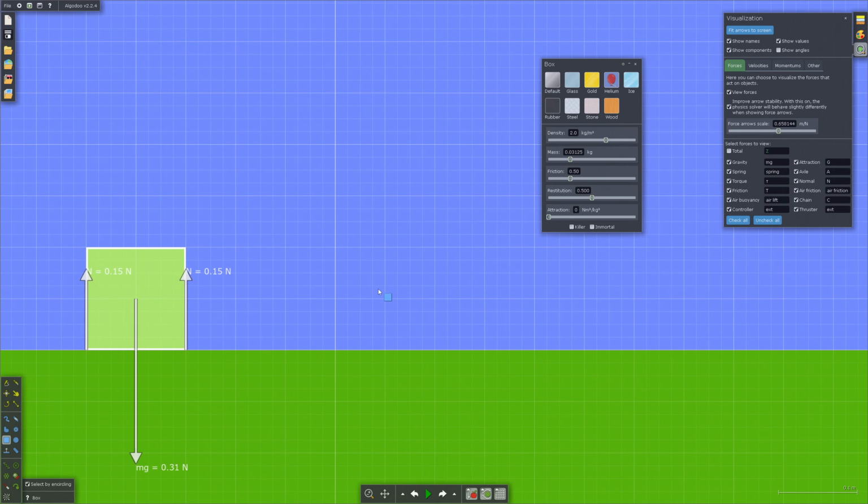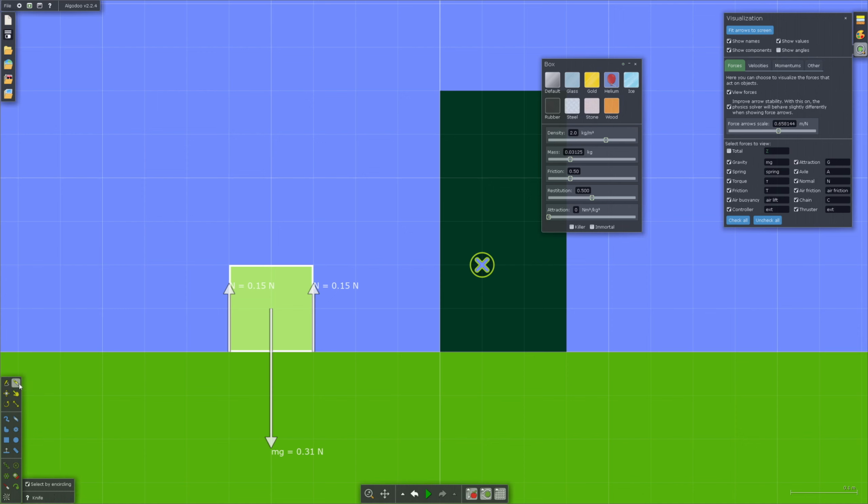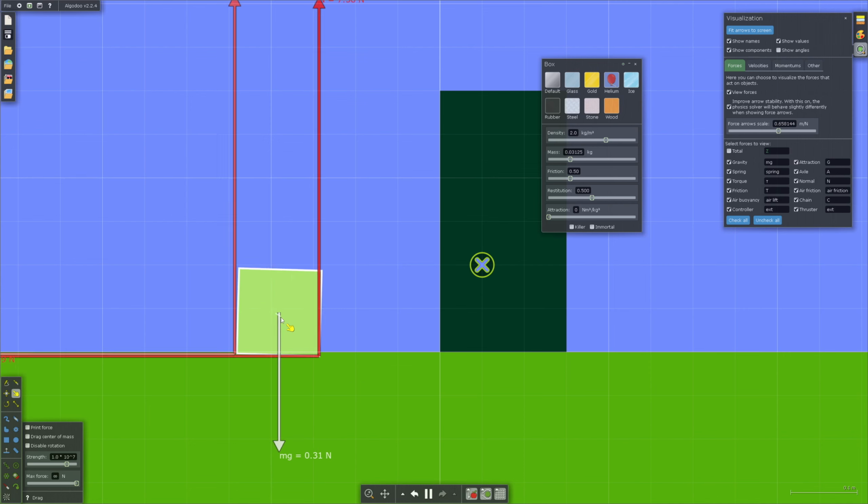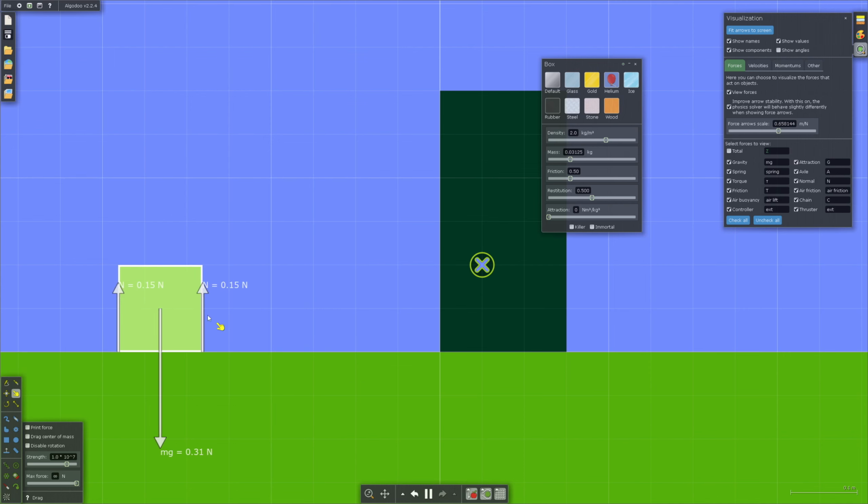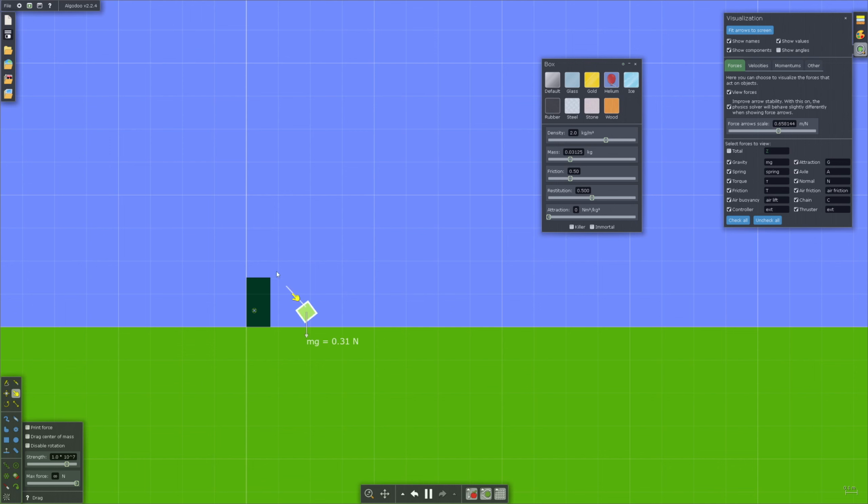because we have to create another mass which basically will be our wall. So this is the wall, the mass M2, okay? And we will make this mass exactly like an ideal wall. To do so, you have to click on fixate. So this mass cannot move, and it is basically our wall. So now if I try to apply a force, let's apply a force to this guy. Let's run the simulation. As soon as I apply a big force, boom, it will just bounce like any wall would do.